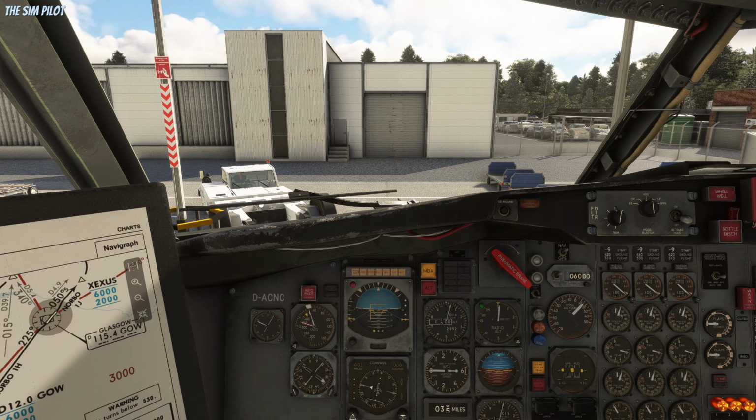Those are the values that I get from the included charts in the manual. We'll pitch up to 17.5 degrees, and then we will lower the nose down to 12.5 degrees to clean the flaps. And once we are at clean flap speed, we are going to command a 7.5 degree pitch for the rest of the climb and set our EPR accordingly.